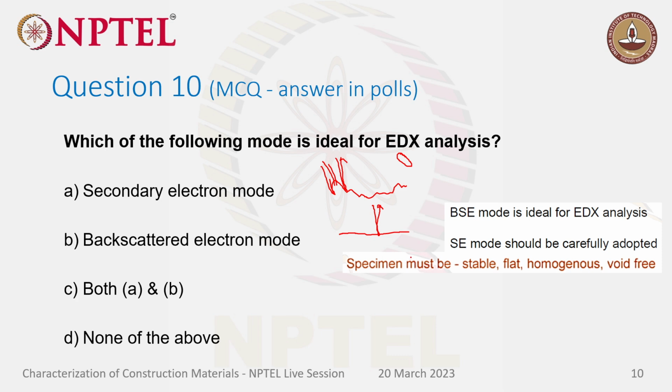I hope in some of the lectures, if you see the second part of the lecture on SEM, you will get to see more SEM images, and the professor would have described which one is a hydrated phase and which one is not hydrated, and how we can differentiate based on the contrast and all. So you'll get to know that voids or pores will appear dark in the SEM analysis if you take the image. I hope you guys got it right now.